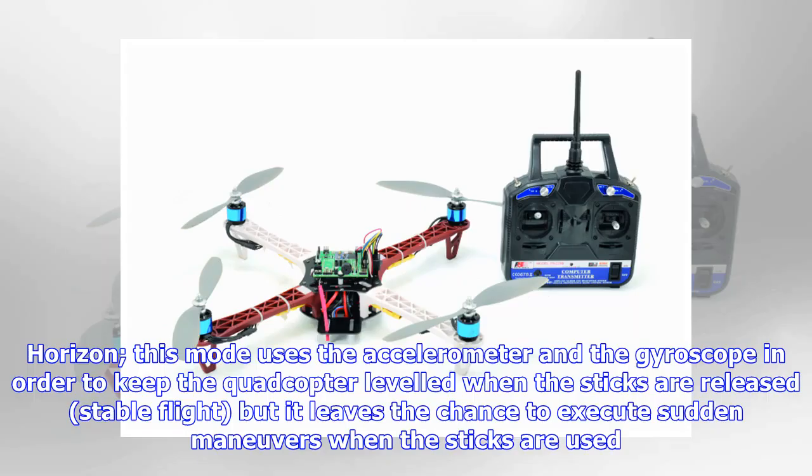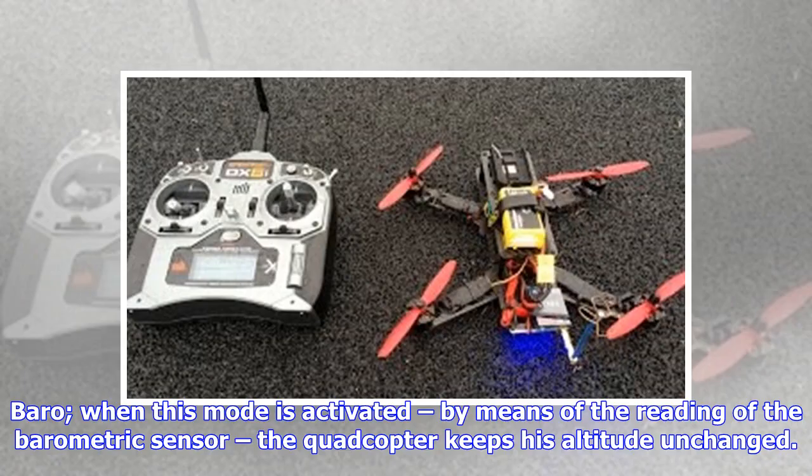Horizon. This mode uses the accelerometer and the gyroscope in order to keep the quadcopter leveled when the sticks are released. Stable flight, but it leaves the chance to execute sudden maneuvers when the sticks are used.